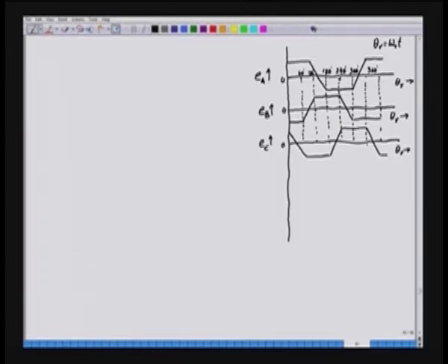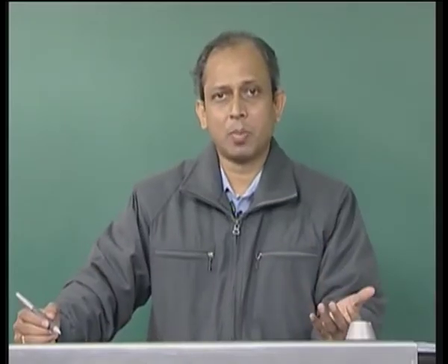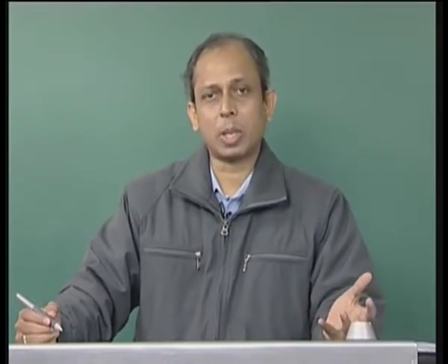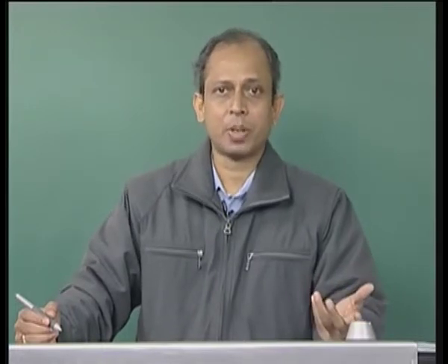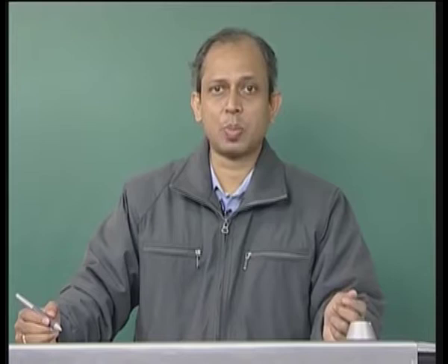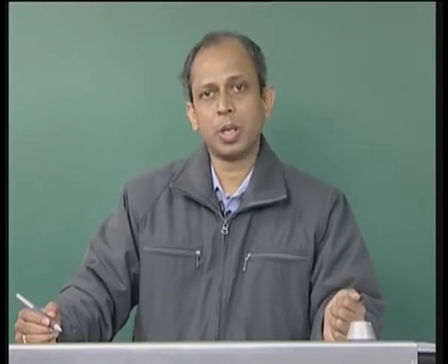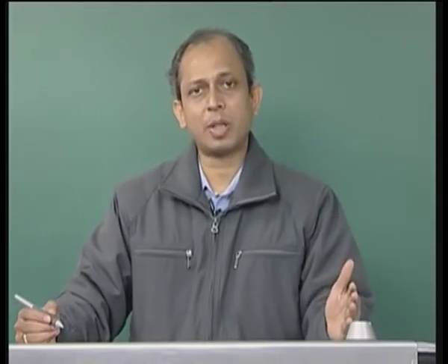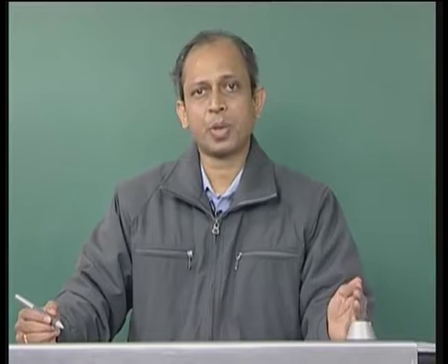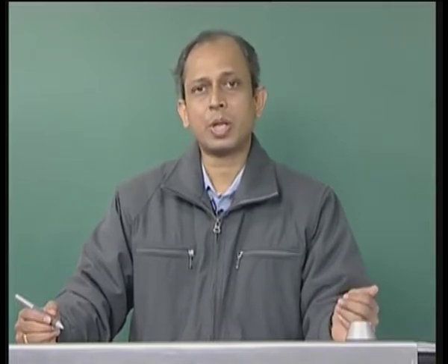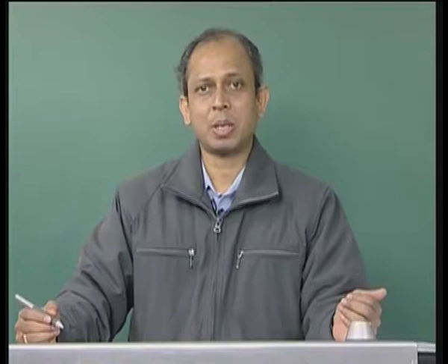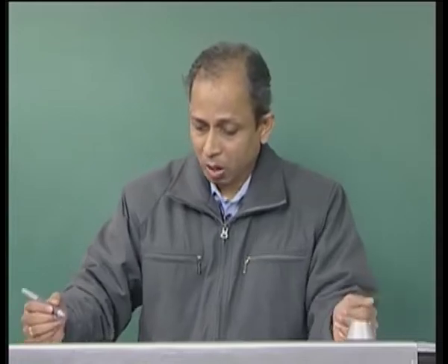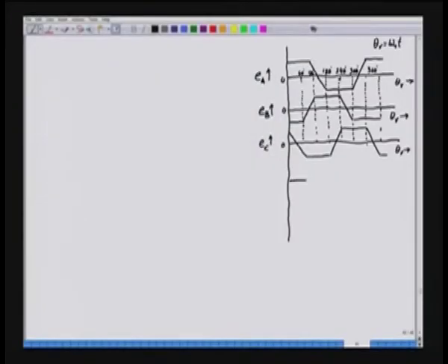And how do we control this kind of motor? We have a trapezoidal excited permanent magnet motor, and we would like to control it like a brushless DC motor. Since the back EMFs, or the induced EMFs, of phase A, phase B and phase C are not sinusoidal but trapezoidal, we excite the respective phases by quasi rectangular current waveform. So, the current of phase A looks like this.